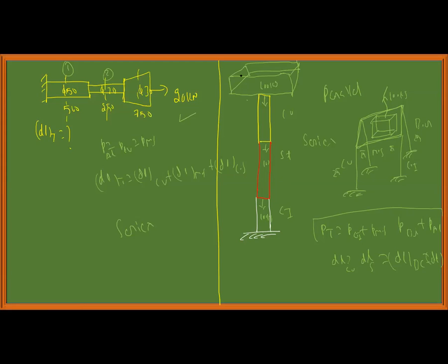So in the context of this problem, this holds good. Our load remains the same. Therefore, each and every section's load remains the same. Therefore, P of AB deformation is equal to 20 into 10 power 3 into length 500, divided by area 50 pi d square by 4 into Young's modulus. Similarly, you should do section 2 and section 3.